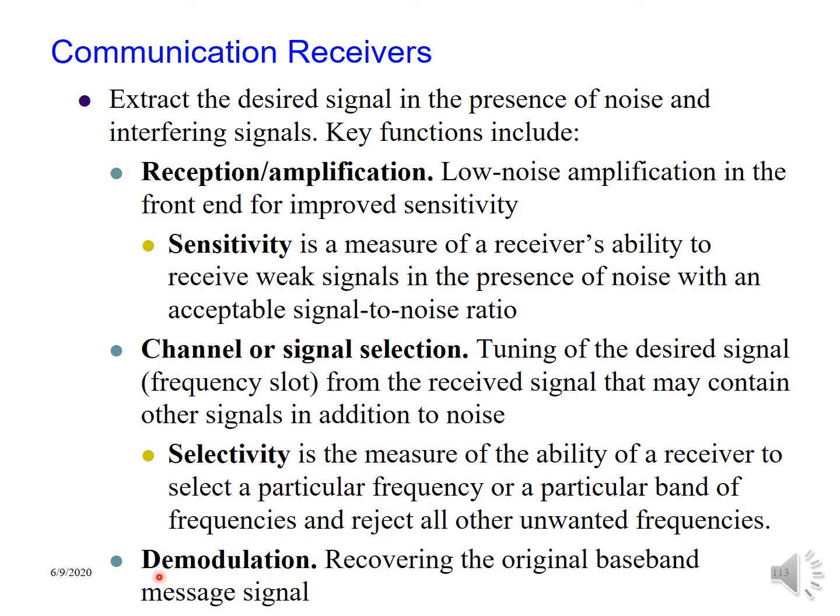And of course, the important part is the demodulation. If you don't know how to do this demodulation, there is no point receiving the signal, because we cannot recover the original message signal. So in order to do this, we have to know the carrier frequency of the transmitter, so at the receiver we know what to multiply.